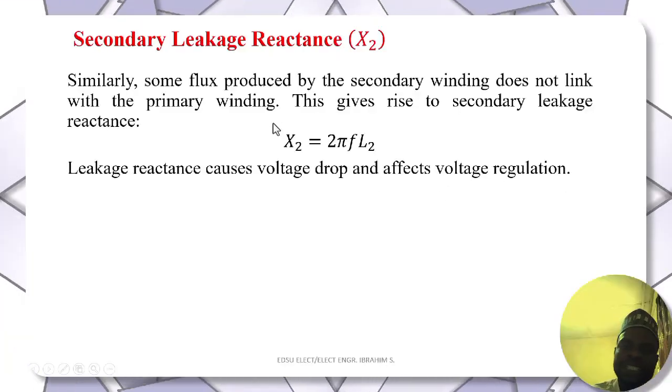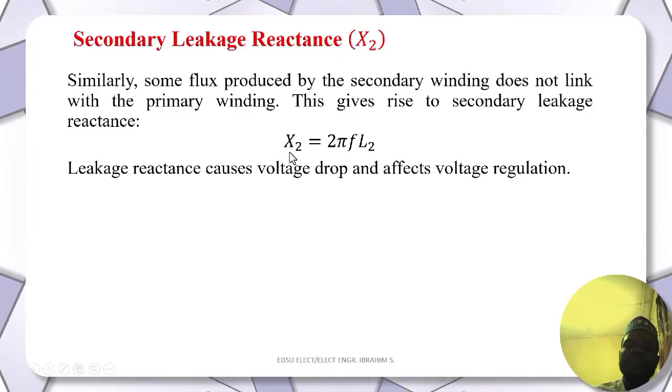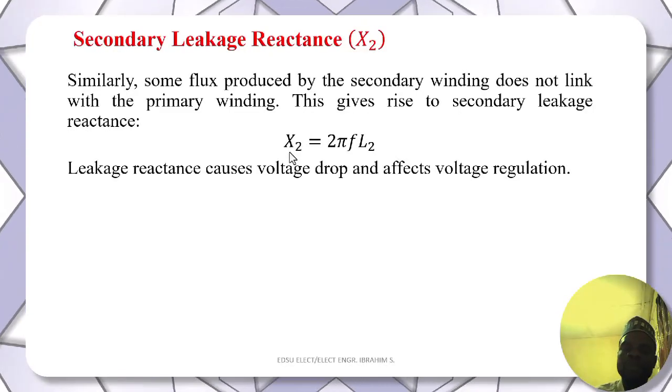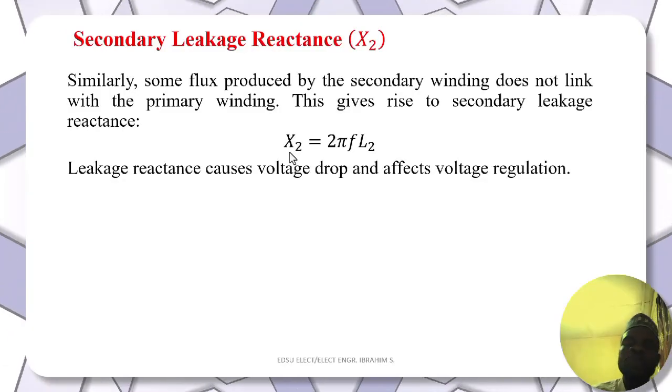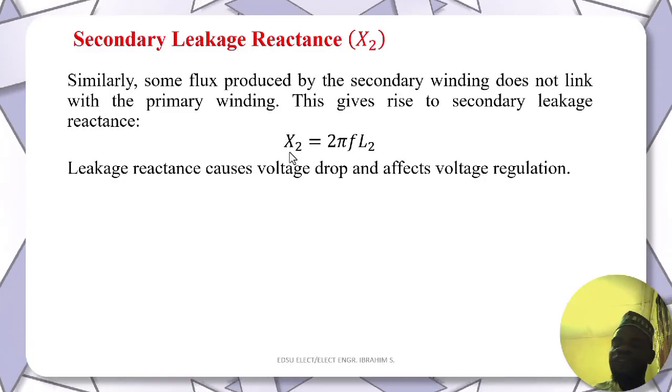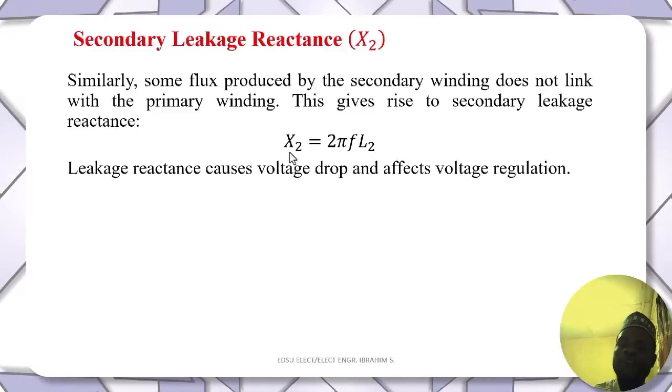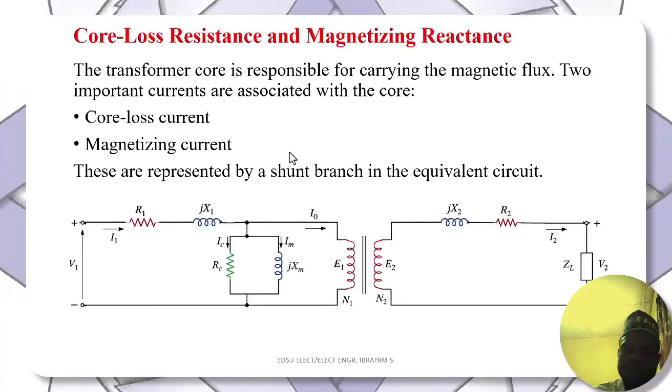Because of this leakage reactance, it will make the normal voltage that was supplied to the circuit drop a little bit, right? So because of that, we have an effect. Then because of that, it will affect the voltage regulation.